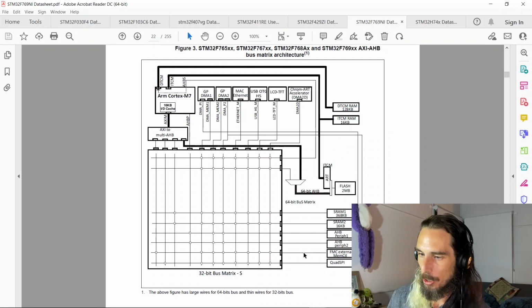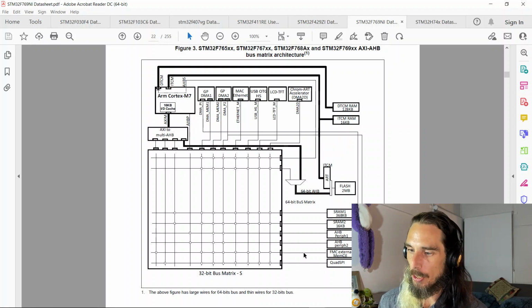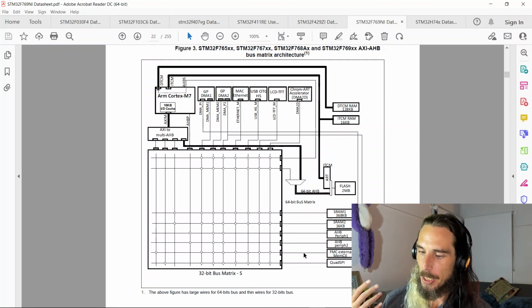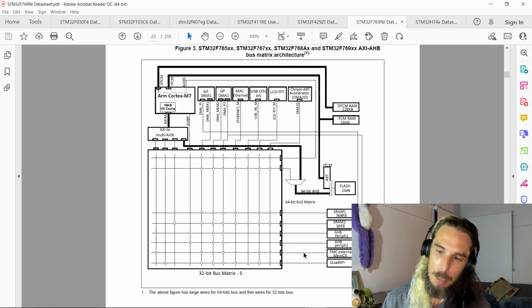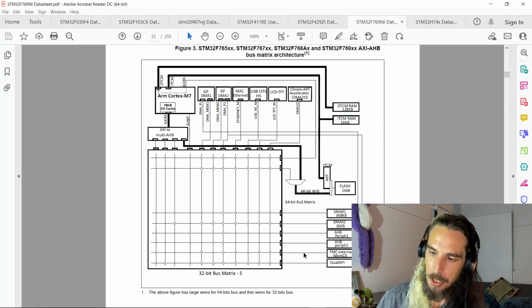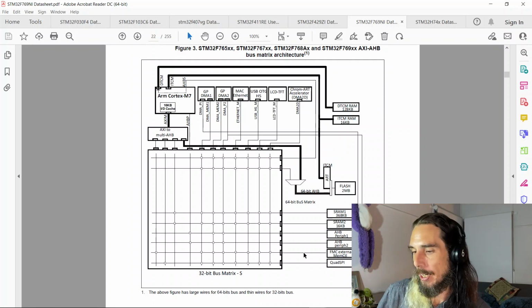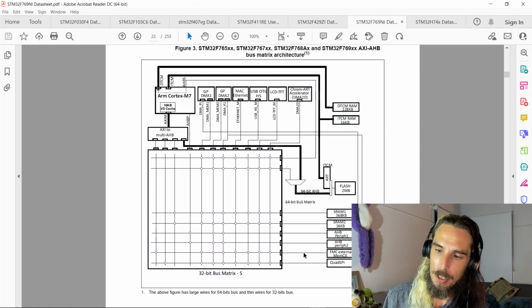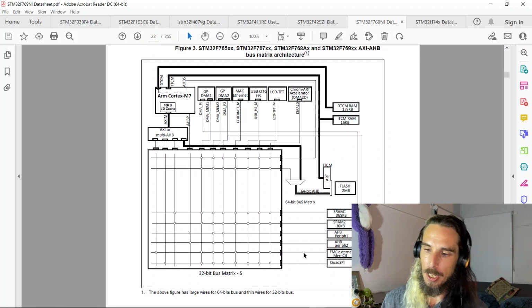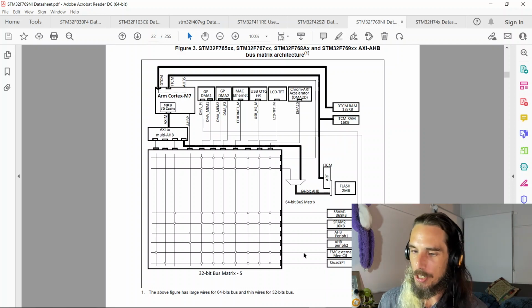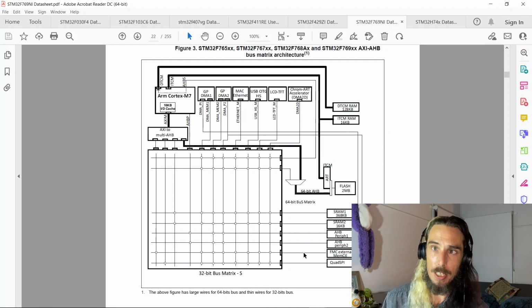Like, for example, on the F769 Discovery board with the bigger touch screen, there's certain situations where you're getting the LTDC peripheral to push a huge amount of data from RAM to the LCD screen, but you're also trying to do things like audio processing and get the CPU to be processing data while you're streaming audio data with the DMAs, you can get into situations where you will start to see things stutter.